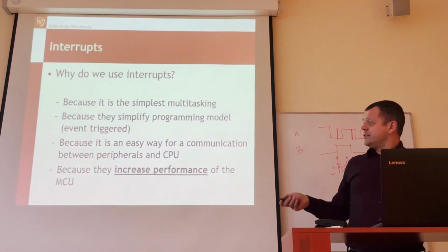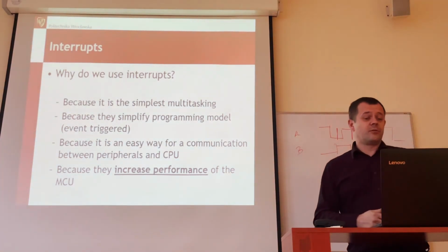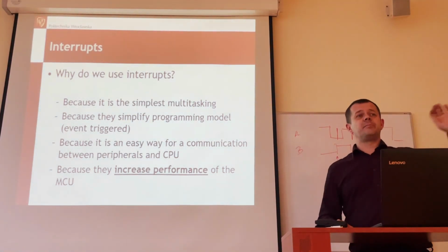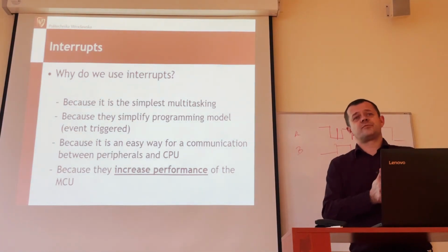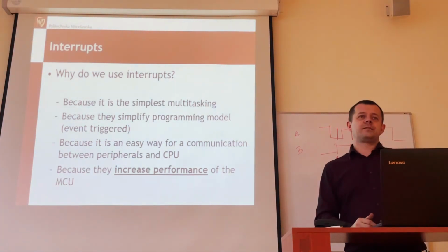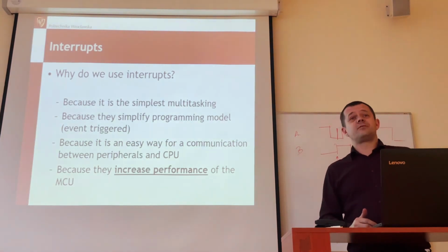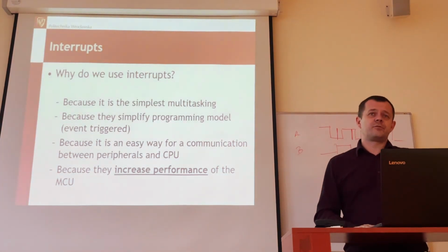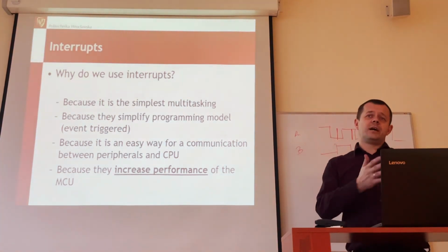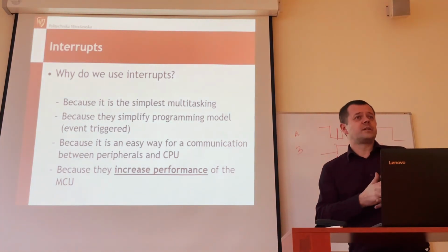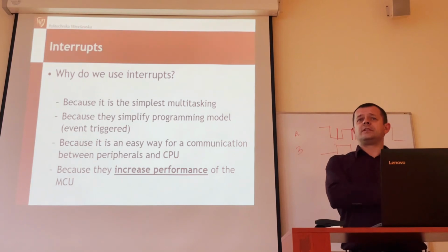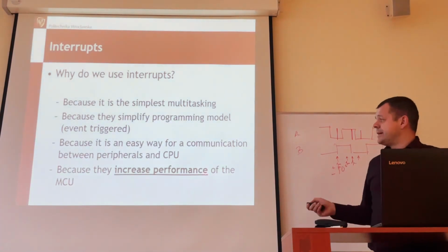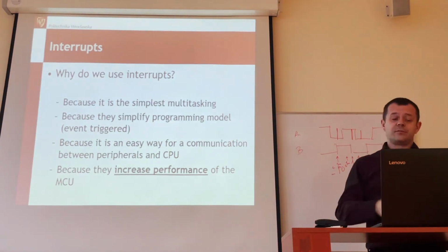And naturally, all this is because we get higher performance. That's why we use interrupts today, and we use them very extensively. My beloved example is the microcontrollers from today compared to the microcontrollers from the past. In the past, microcontrollers tended to have 3, 4, 5 interrupt sources. Today, we talk about a few thousand interrupt sources in one microcontroller. So we can service an interrupt coming from a few thousand various events happening within the microcontroller: peripherals, internal, external pins, state of the microcontroller, many things. So the interrupts are really helping us to increase the performance of the microcontroller.